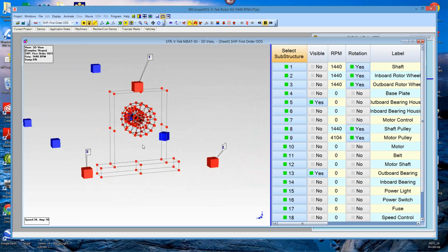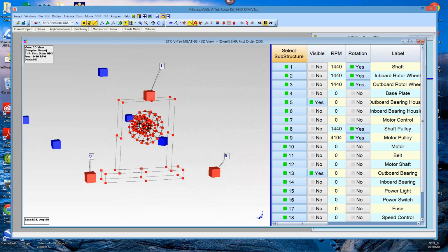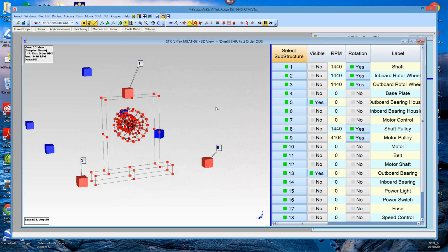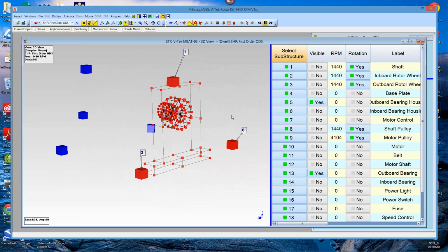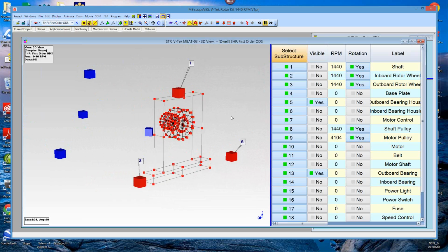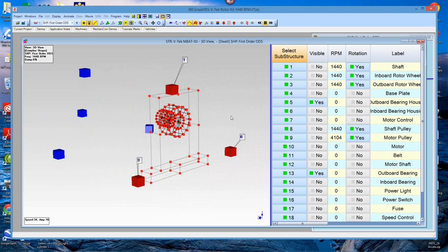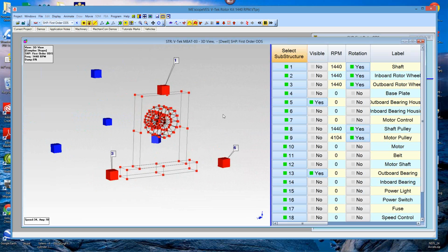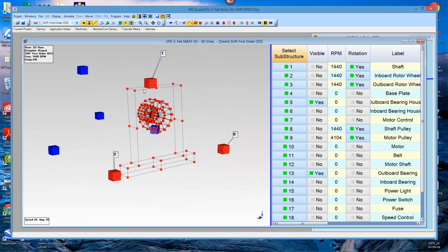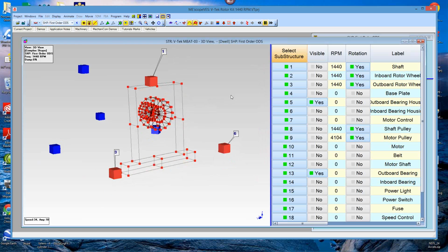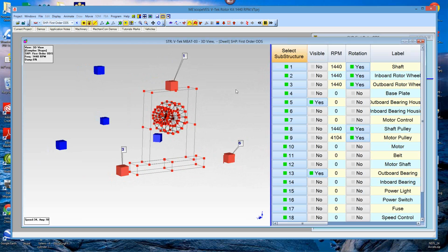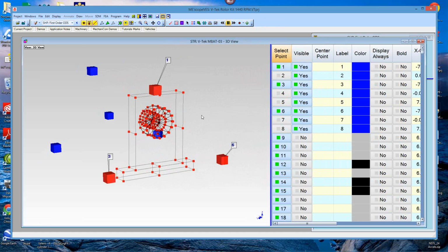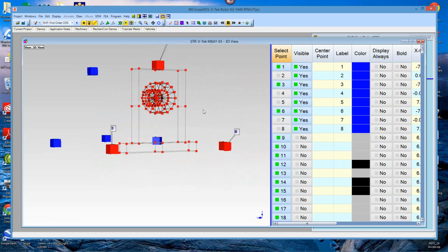However, the center, which is going to house the shaft, is not following the accelerometer on the top of the bearing block. So I'll go in there and just grab the top portion of the bearing block and make that follow the accelerometer sitting on top of it. So I'm going to go back and stop this, and let's just go in and select.